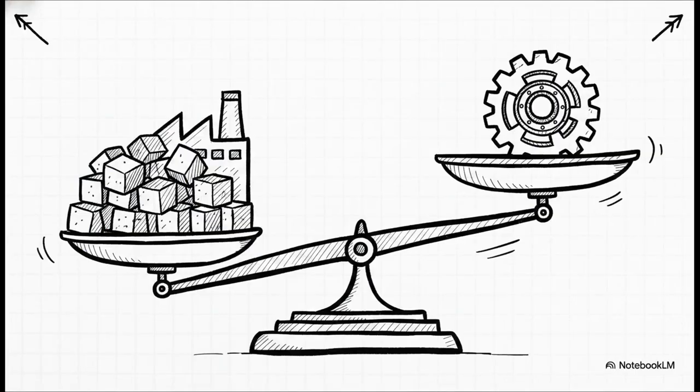Now, you might be wondering, how do engineers actually decide which process to use? Well, it's a huge balancing act. They have to weigh several crucial factors like the material's properties, the complexity of the product design, and the production volume. For example, if you're making 1,000,000 of something, high-volume production might totally favor casting. But if you need incredibly high precision and super tight quality tolerances on a really complex part, you are definitely going to choose a cutting process, like CNC machining. It's this constant tug-of-war between cost, efficiency, and precision.